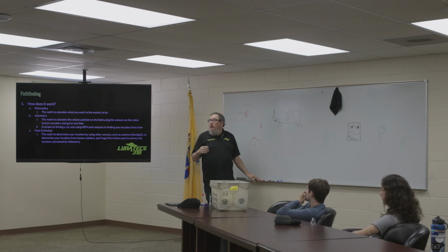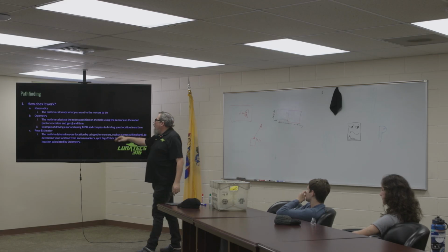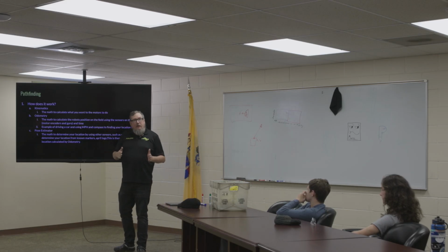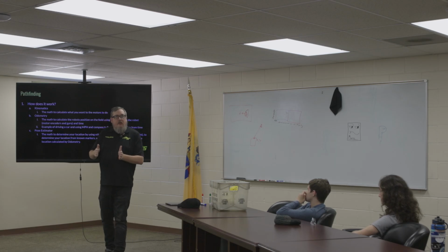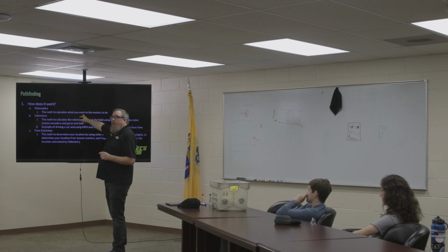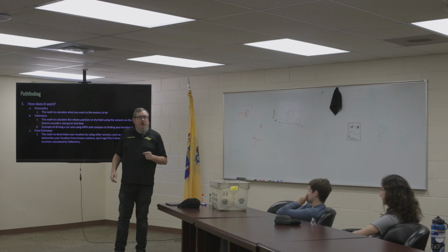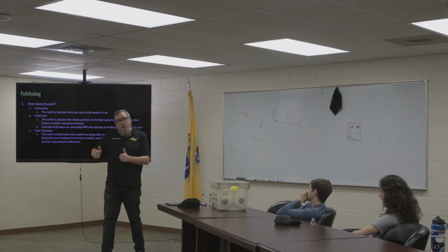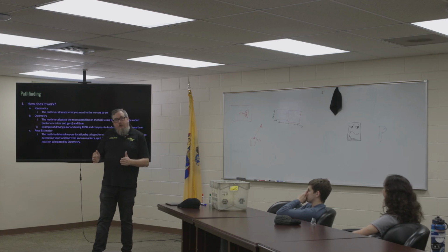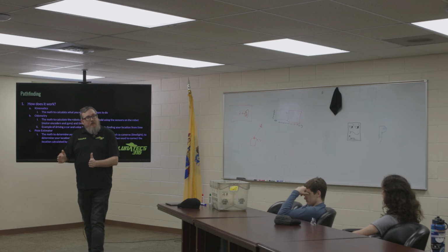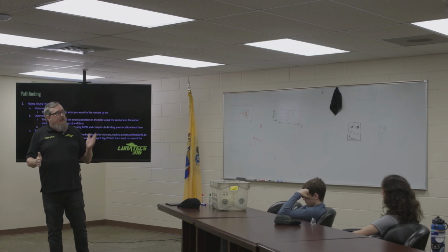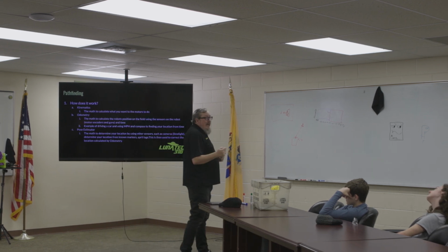And because I know where I am on the field, I can then correct my odometry and make slight corrections to match my path, which we calculated with kinematics. So that's why it's called path finding. You're following this path that was planned out for you, and the odometry is trying to follow that path. And then all of a sudden, the Limelight's like, oh, you're off path. So it slightly swerves you back on the path. And that's how we get really precise accuracy.